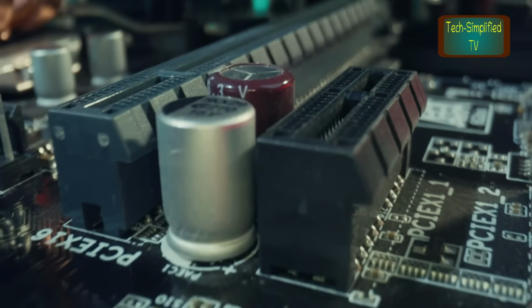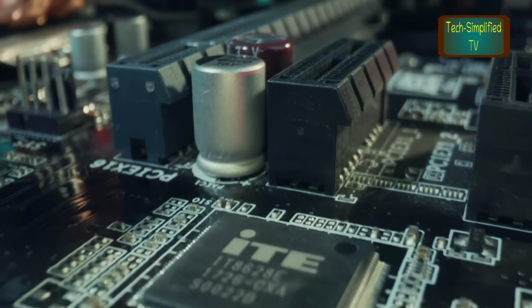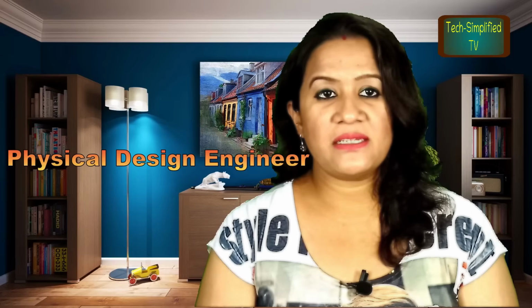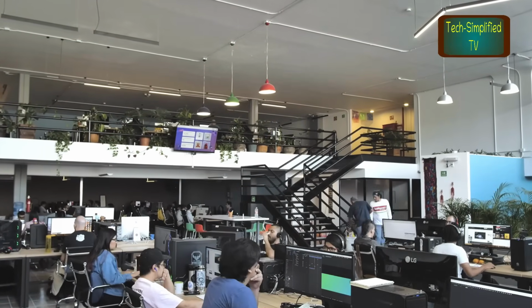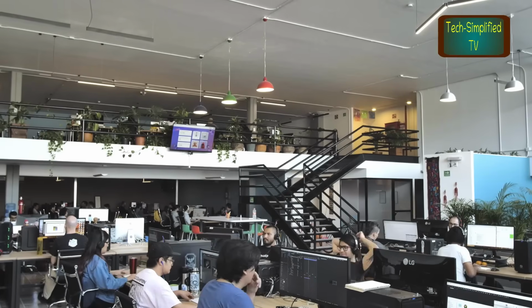So basically floor planning, placement and routing, timing or STA, power budgeting and area implementation, ECO tasks, that is timing and functional ECOs to address functional bugs and timing violations, physical verification like LVS, DRC, etc., noise analysis, electromigration, antenna checks, all this comes under the job role of a PD engineer. Obviously, it should be a big team to perform and complete all these complex works.